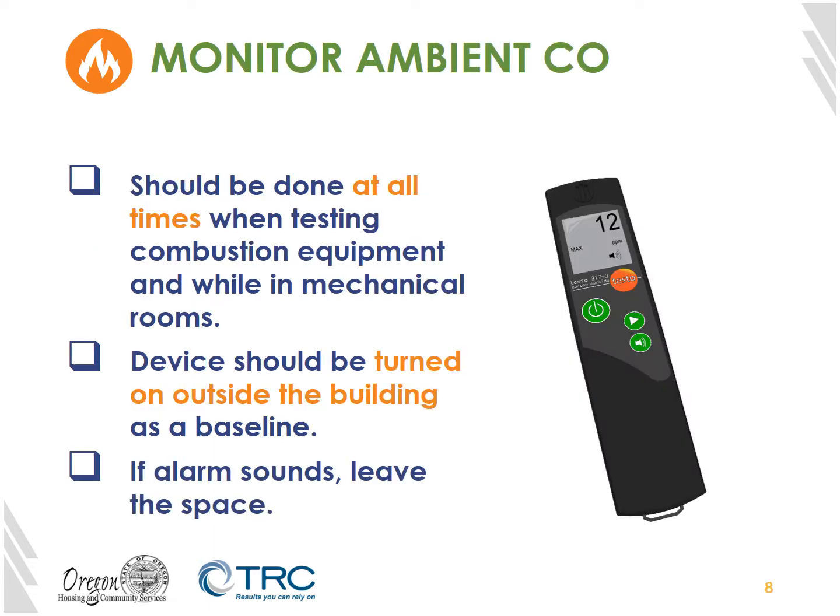For combustion safety testing, we also want to monitor ambient CO. Monitoring ambient CO should be done at all times when testing combustion equipment and while inside of mechanical rooms. The ambient CO monitor should be turned on outside the building to zero it out or establish a baseline. And if the alarm sounds, you should leave the space because it's indicating that CO levels are too high.